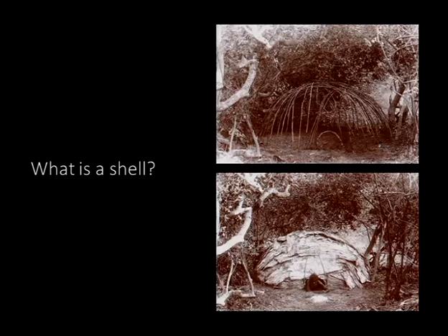We should imagine a joist of the houses you are studying. The thickness of this joist is rather consistent. But what happens in this case? You see that these elements are so thin because somehow the forces are distributed along the elements and there is never bending. So the idea, in order to decrease the thickness of structures, is to avoid bending.